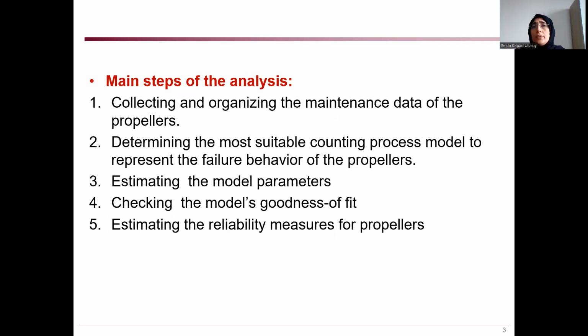Main steps of the analysis: first, collecting and organizing the maintenance data. Second, determining the most suitable counting process model representing the failure behavior of the propellers. Third, estimating the model parameters. Fourth, checking the model's goodness of fit. Fifth, estimating reliability measures for propellers.